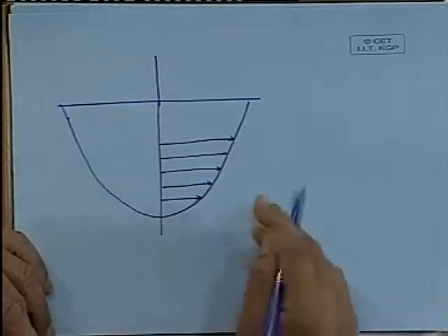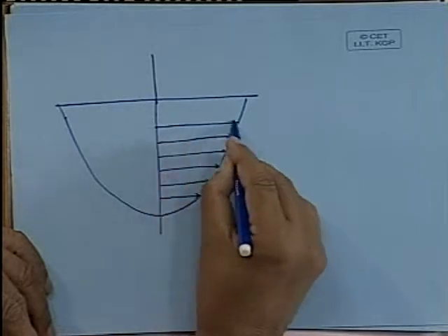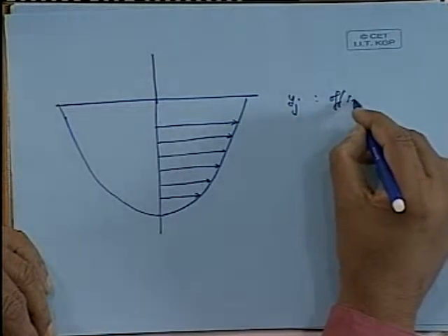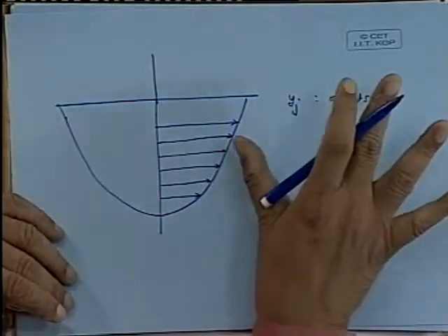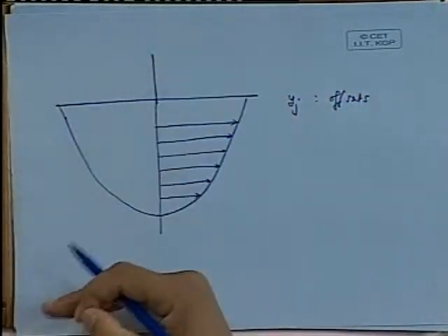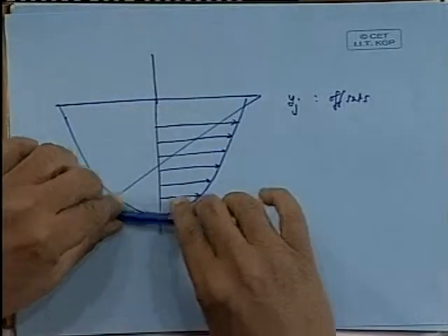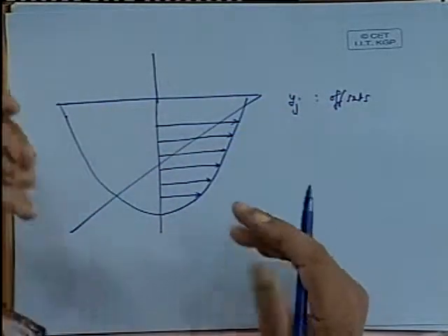See, this is the water line. This I am drawing at equal intervals. These water lines. See, the offsets normally are available to a naval architect in a tabular form or in some form. You would want to use those numbers in a computer program. You don't want to actually pick up. See, if I have this line, if I have to now go and measure by a scale and feed them, it is a tremendous job. Earlier days we were doing that, but what I want to tell here is a method where the offset becomes the input point, which is already there for your hydrostatics. You don't have to do any extra work.